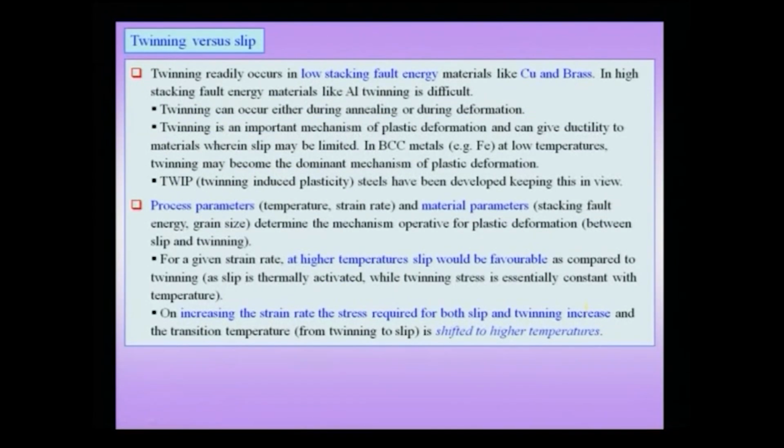Of course, when a dislocation reaches a grain boundary, either it may be absorbed by the grain boundary, or it may become a dislocation associated with the grain boundary, or it may initiate slip in the next adjoining grain, in which case it continues to slip through the polycrystal.